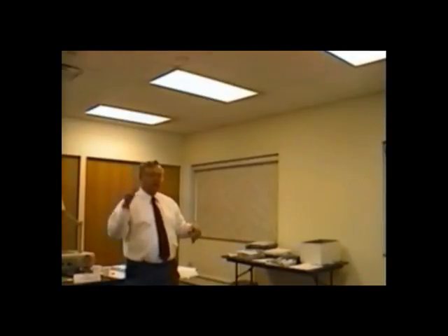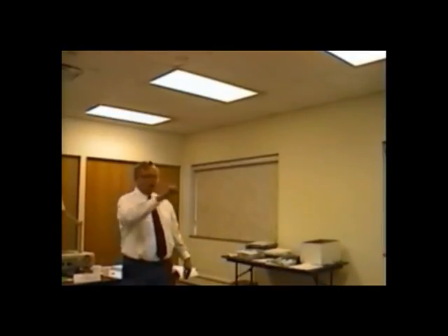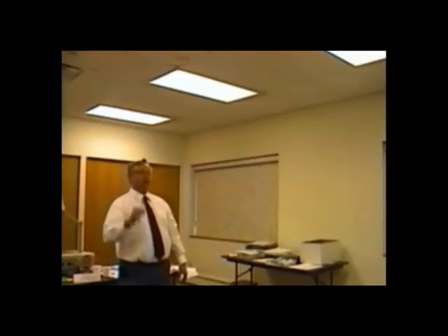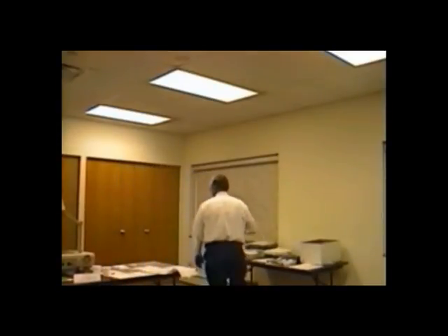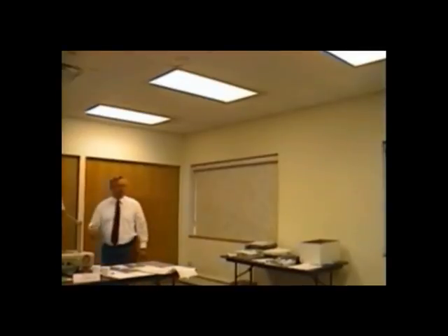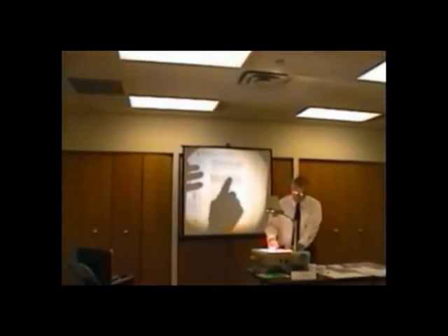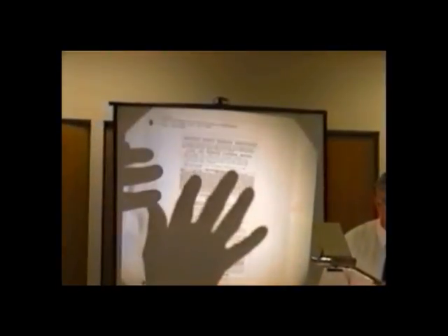But again, if you got an orifice, that statement says start with the pressure chart and then come back tomorrow when the house is cool so you can finish it by the superheat chart that's on this chart. That's what that says. You have to bring it down within 2 degrees of the normal comfort system in order to finish the chart. So we can start with the pressure chart. I'm not going to spend time going through this.